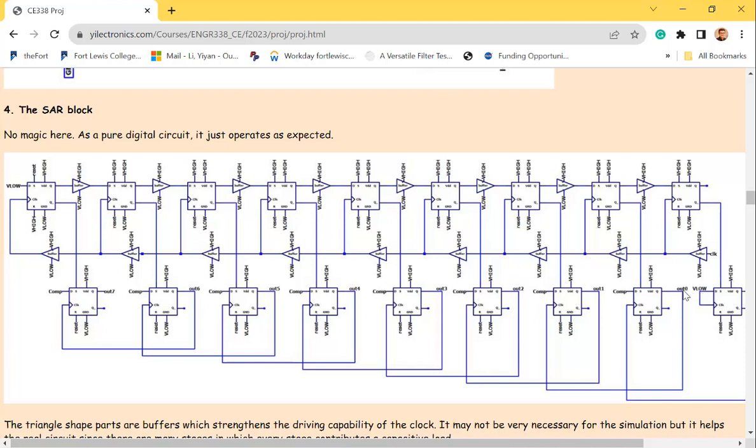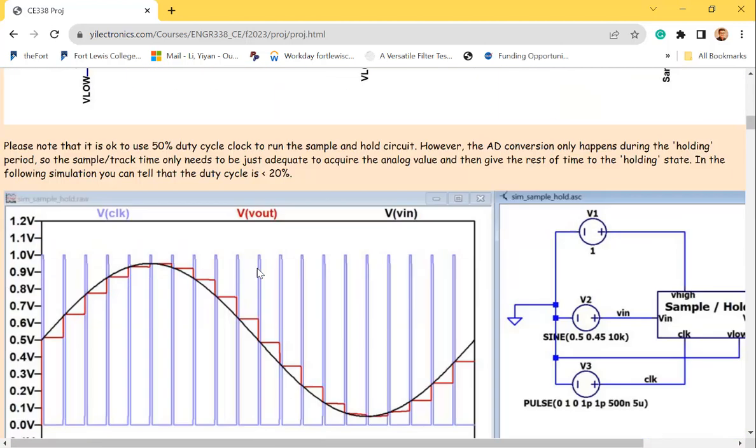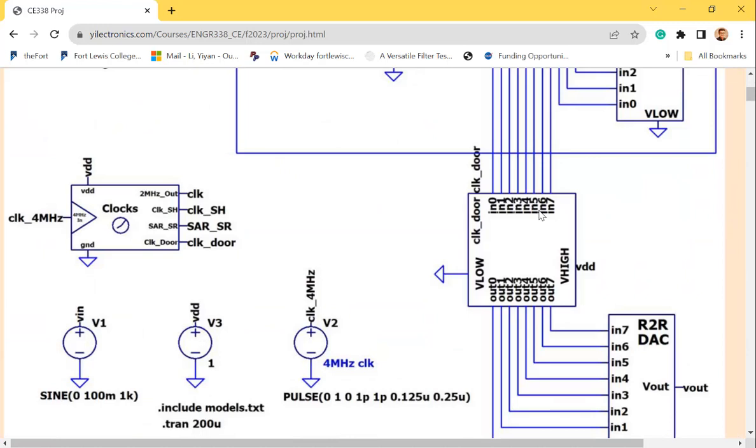The reason we need one more cycle is because we are using the same clock, there's just one clock. At the rising edge of the clock, it's going to do something at the same time. So at the 9th rising edge of the clock, we have the final result. There will be a little bit of time delay, but at the 9th cycle, you are expecting to have the final result over here. So the correct digits will appear here. But at the same time, do you want to kick it out by using the same clock? See here, this is a parallel in, parallel out flip-flop array. At the 9th cycle, the rising edge of the original clock, which is here, which one are we using?